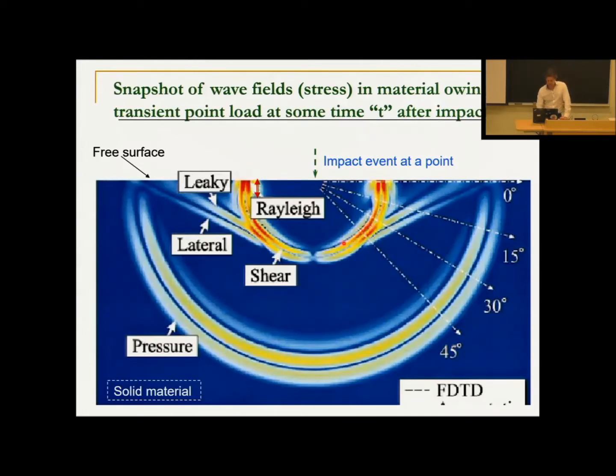But near the surface, we see that the shear wave hemisphere flattens out, and we have large amplitude, indicated by the red color, of energy, and that's the surface wave. It's kind of relegated near the surface, and it propagates along the surface, and it's distinct from the shear wave. It's about 10% or so slower than the shear wave, so it lags behind the shear wave. So the farther this propagates, we see more of a flattening of this hemisphere, right, as the waves continue to propagate, right?